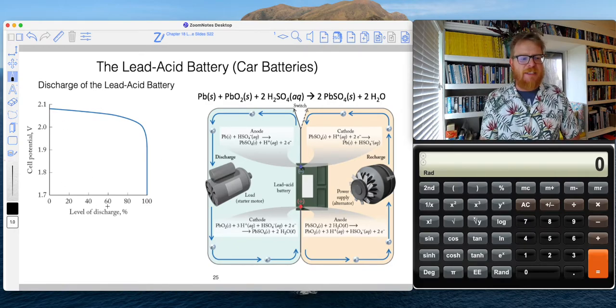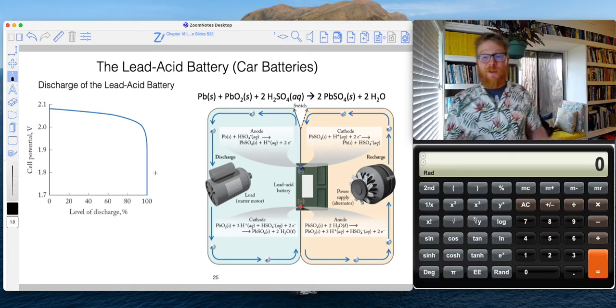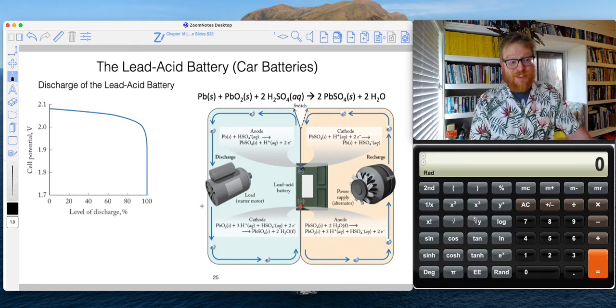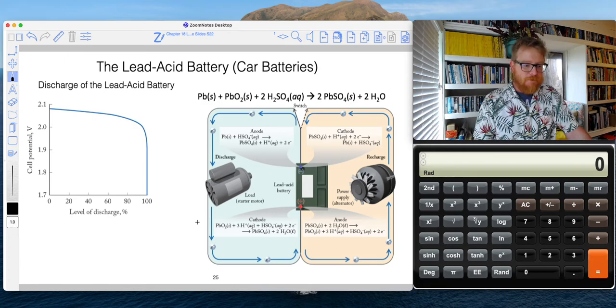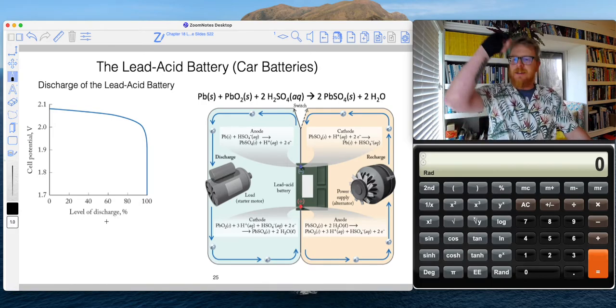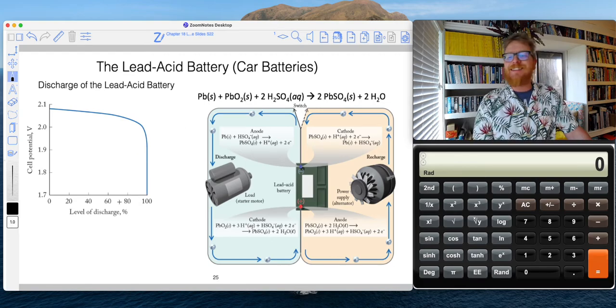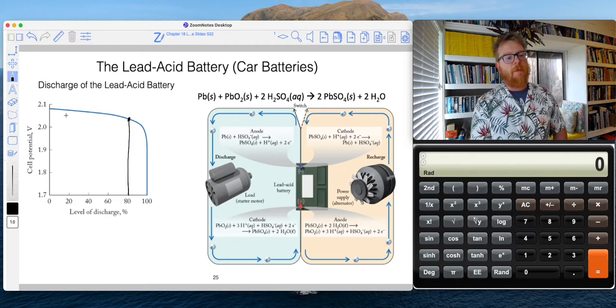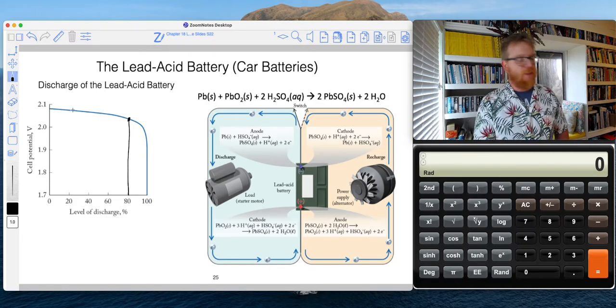And so this gives you an idea of how much you can actually discharge these things. And this is what I was talking about, how in reality, we really only use like 25% of our battery or so, okay? Because when you see that, that's a really sharp fall off. So when we look at this level, or excuse me, not 25%, I knew I was backwards on that, roughly 75%. So I'm gonna draw a line, around the 75, 80, let's just call it 80, okay? So we're starting at about that 2 volts or so, 2.04 volts, right, for one of those things.